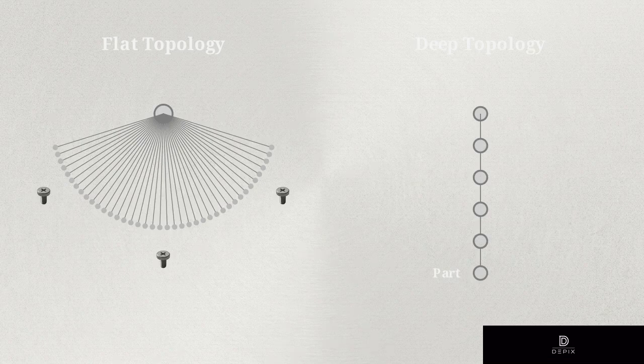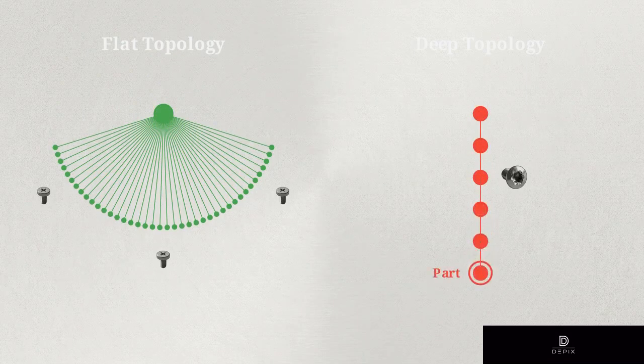Every time you step deeper into a dependency graph to reach the next layer, you introduce a new chance to snap a ribbon cable, strip a screw head, or tear a water seal. The math of repair is unforgiving. Removing 40 accessible screws in a flat one-layer layout is always faster and safer than carefully extracting just 6 screws in a deep, layered structure.